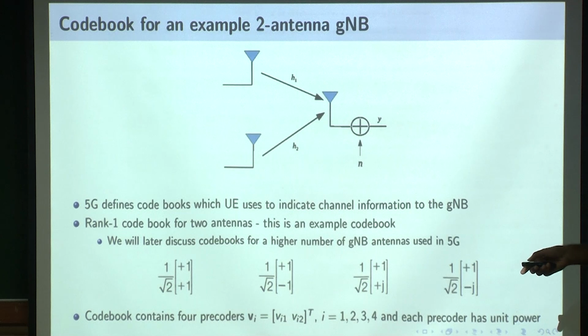This one, right. So what is happening here is, when you do this operation, the precoder entry which is getting picked is helping the channel get added in phase. And you could say, but the angle could be slightly different, it need not be exactly 90 degrees; it could be slightly lesser than that, 85 degrees, 70 degrees, 50 degrees.